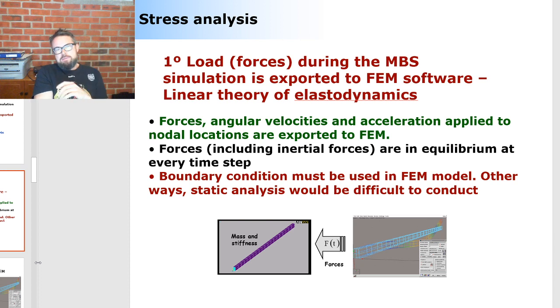Once you get the displacement, then it's possible to use this kinematic matrix that we discussed a few weeks back. Take the kinematic matrix and estimate the strains from displacement, and then you can use material properties to estimate how much stress is applied in your structure. So this is the method from beginning to end.